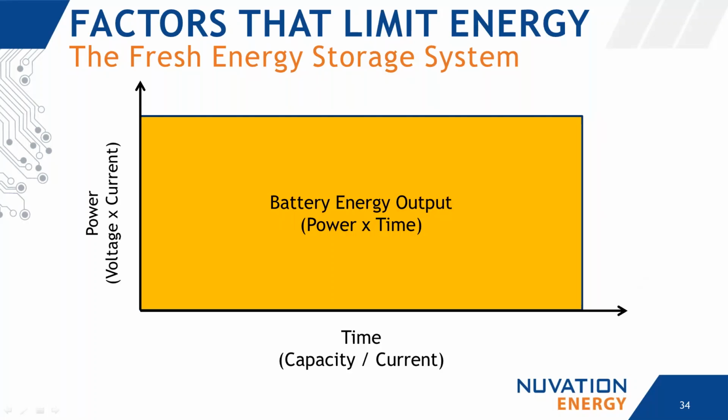Let's think about what limits an energy storage system. You have a specific rated power on your design. It's quite common that an ESS is rated at a power that is actually below what the cells are maximally able to deliver. And the reason for that is actually tied back to those examples that we looked at.